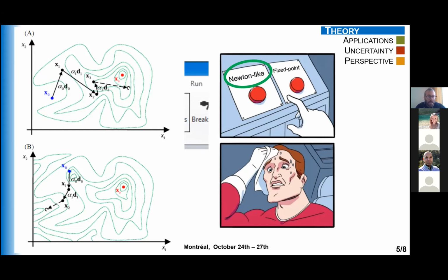These methods are faster than fixed point, but are very sensitive to initial guesses. Use them when you have a small number of recycles, and when these recycles are not nested, so they are not recycled in recycle loops. Also, pay attention to problem initialization. On the other hand,